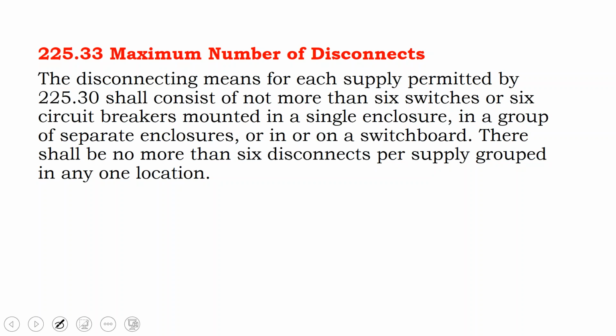But the main rule you need to know when determining how many supplies, if you have a generator, a battery bank, maybe a second battery bank, maybe a second generator, a large generator and a small generator might have separate purposes, or on a microgrid, having a lead acid battery bank and a lithium ion battery bank operating in parallel might have special purposes. So who knows? The rule for determining how many supplies, or even how many loads for that matter, on a service panel is, if you have more than 6 switches, you need to have a main switch. So if you're designing a utility scale solar farm and you have distributed inverters and you have 7 inverters on a panel, that panel needs a main breaker or disconnect switch.